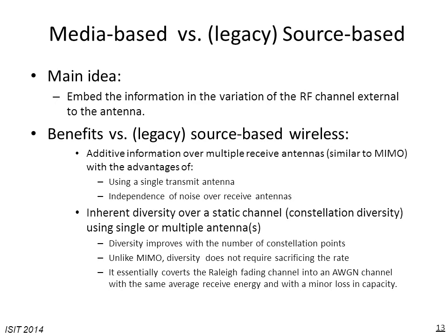Now coming to the second sub-bullet, essentially this means that in a 1/k media-based modulation, unlike MIMO, unlike a k/k MIMO, achieving or increasing diversity does not require sacrificing the rate.